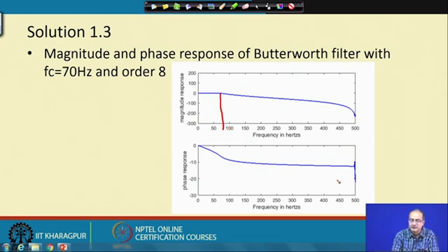and we will see that there is some impact, that probably it has gone a little higher than -100. So, as the cutoff frequency is moving right, the suppression is not that prominent, but the model order has more impact, that we can see. Okay. And the knee point also, from where it becomes constant, has moved and come near the 70. So, these are the different cases we get.